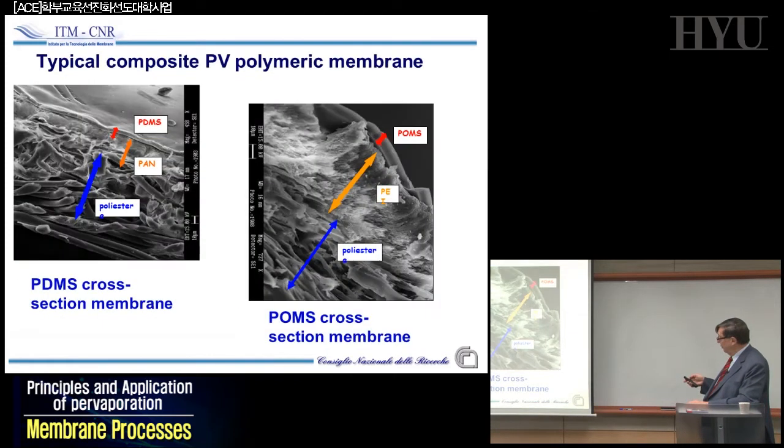And again, just to mention that if this thickness is 150 microns, the real membrane, what is really controlling the system, will be 1 or 2 microns up here. And that is the problem. That's why membranes are expensive, because if you change the thickness here, using the equation, it is the denominator of your relationship, and a 10% change of the thickness gives a significant change in transmembrane flux.